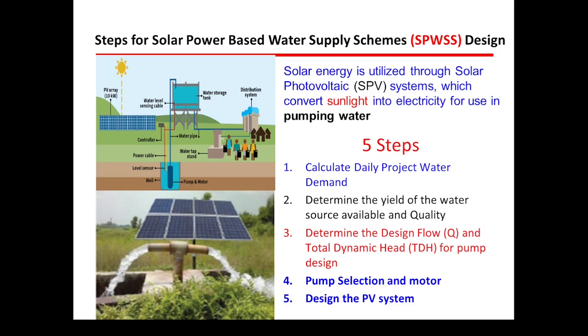When you are going to select your pump, you should consider the step number 3, design flow and the TDH. Then in this step number 4, we are utilizing the manufacturer's software tools for pump sizing.